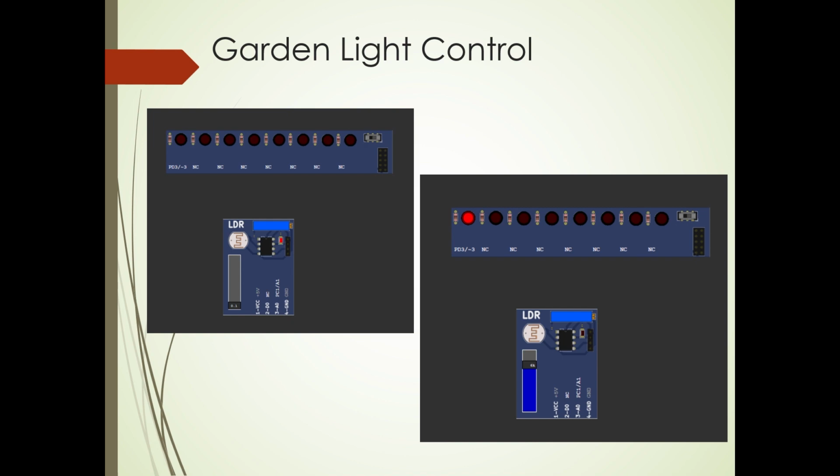When current passes through an LED, the electrons recombine with holes, emitting light in the process. LEDs allow the current to flow in the forward direction and block the current in the reverse direction. Light emitting diodes are heavily doped PN junctions, and based on the semiconductor material used and the amount of doping, an LED will emit colored light at a particular spectrum wavelength when forward biased.